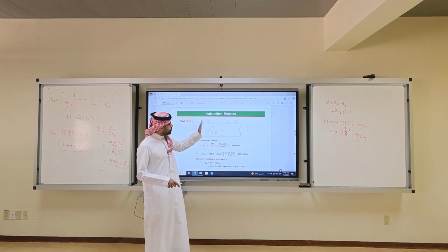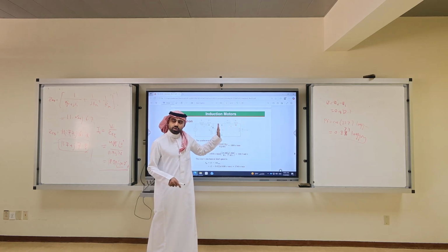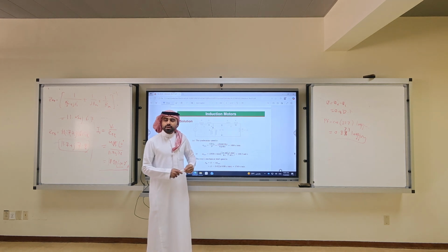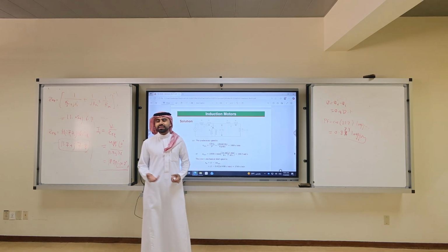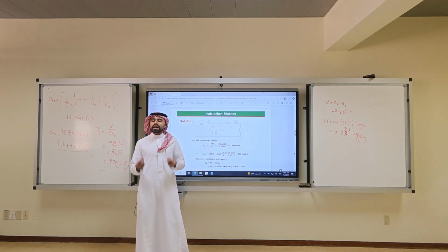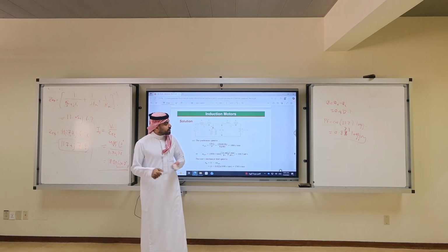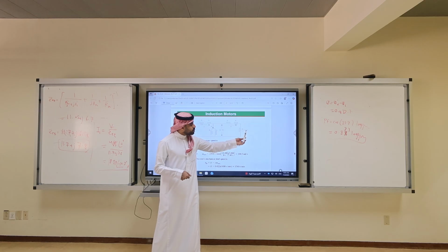The whole thing is the motor, so the motor is the load. But if you ask me the power factor of the mechanical load, you cannot ask what is the power factor of a mechanical load, because a mechanical load will translate into slip.